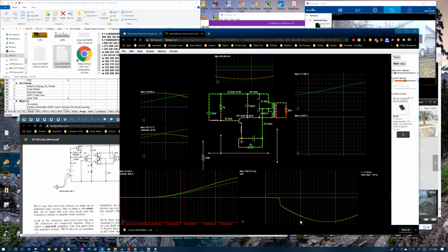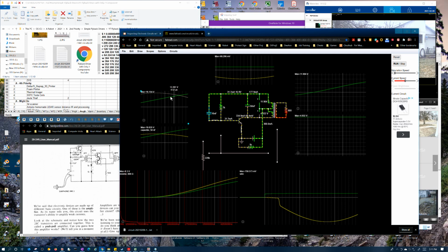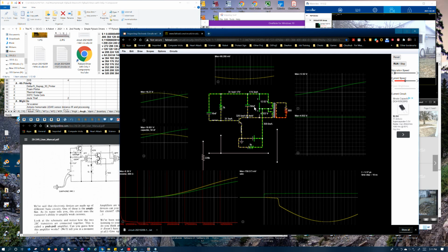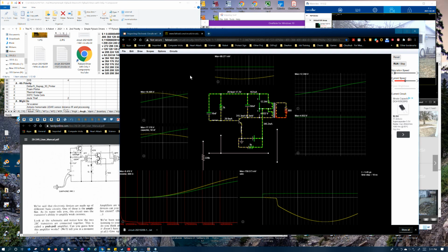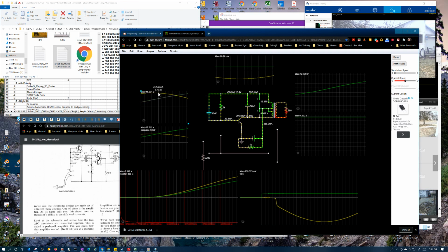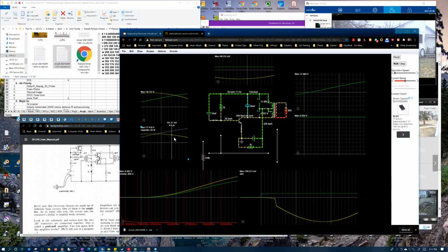As far as I can tell at this point anyway, our base current is falling off here. And that happens as our voltages continue to rise across these capacitors. In fact, you can tell that we're already up to 17 volts from a 5-volt battery here. But the capacitor charging current is definitely falling off now.